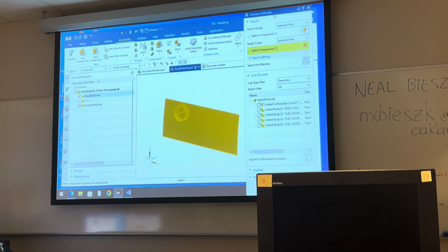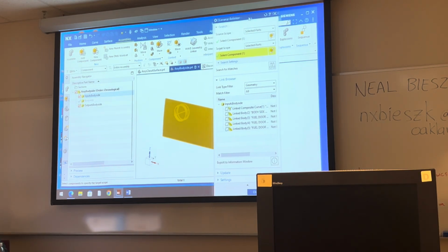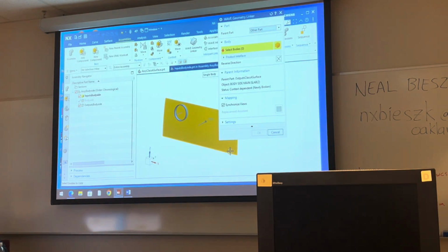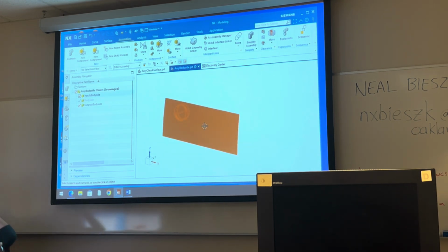Okay, so now I got a bunch that didn't work, all right? When you do that part, you might get like 4 green check marks and 1 that isn't. It might say it couldn't find the main slab. You can right click and go manually relink, and you just pick the correct slab. That's how you fix it if it didn't work with the name. Does that make sense, kind of? Mine worked, so I had to pretend it didn't work. I went to another one.